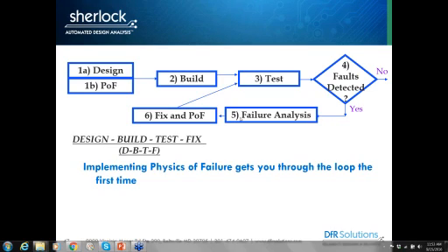But no, Sherlock does not do any electrical analysis on your circuits. It's more of a SPICE type of analysis. But there are places in Sherlock to enter electrical stress data that can be used for derating analysis. The next question is: is Sherlock capable of performing vibration and thermal cycling combined loading for solder joint life prediction?